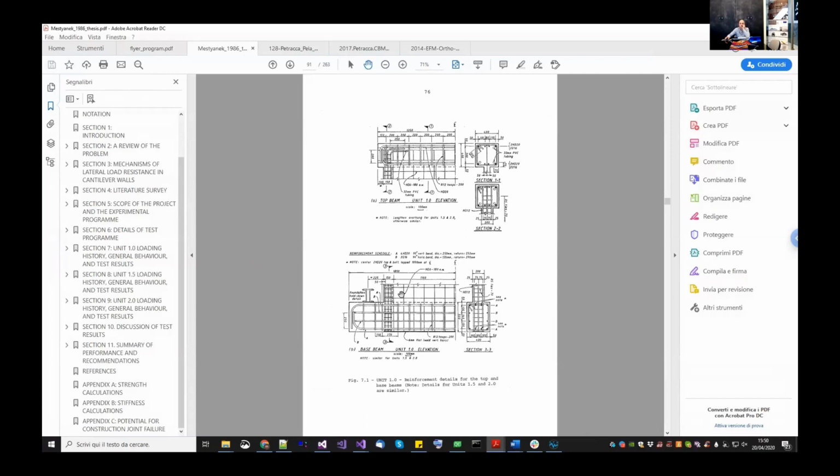Okay, here. Well, basically here in the web, we have 6 diameter rebars every 180 millimeters of spacing. And then we have different diameters in the beam columns. And for simplicity, we are going to neglect the rebars in the bottom and top beam because it is not so important. They're so massive that these rebars are not doing anything in our example. If you want to be more precise, you can change the file that I will send you. So we are going to create 2 layers, one in the 0 direction and one in the 90-degree direction for the web.